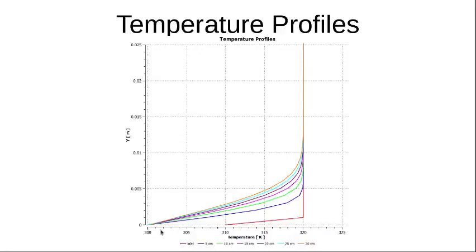And for the thermal boundary layer also, you can see the thickness of the boundary layer at 5 centimeters is this, 10 centimeters, 15, 20, 25. So the thickness of the boundary layer is somewhere close to 1.3 centimeters at the end of the plate. So that is the thing that I was actually trying to show you.